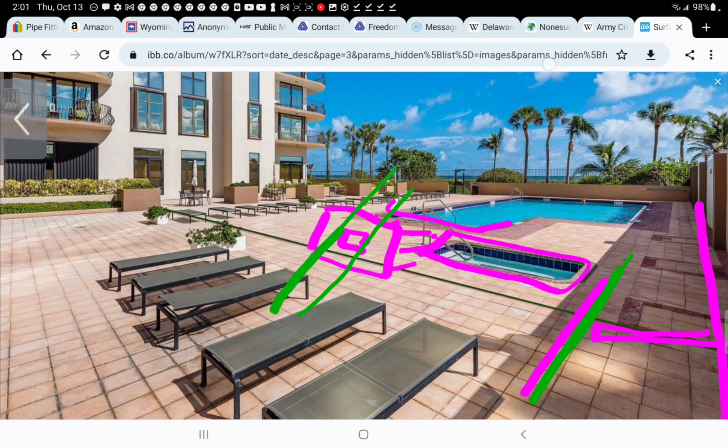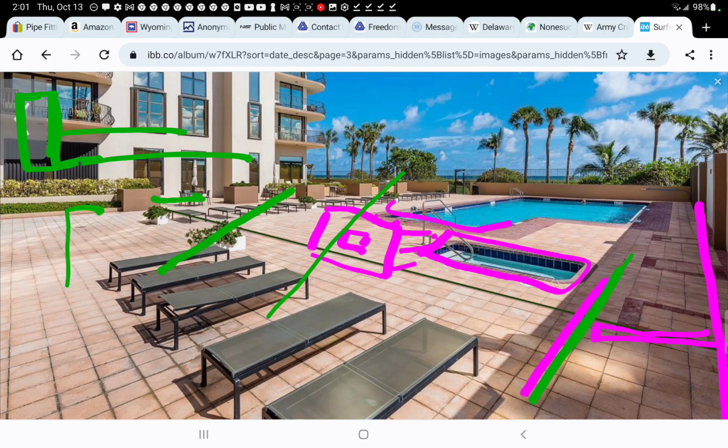Right over the column, wait a minute. Right over the columns. And let's see, back here there'll be another one. So it travels over top of that one too. And it anchors into the structure with 90s, into the drop slab detail, like that. Deck, drop slab detail. It anchors into here like that.